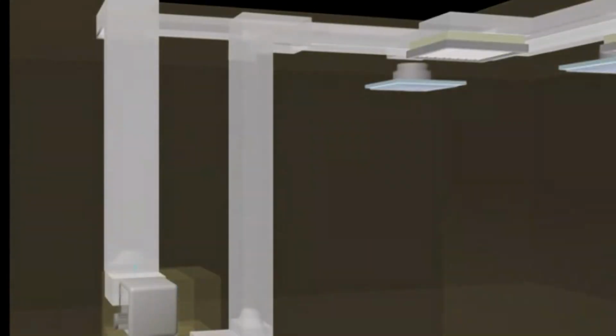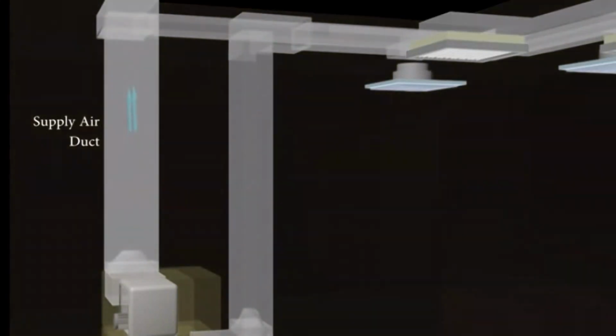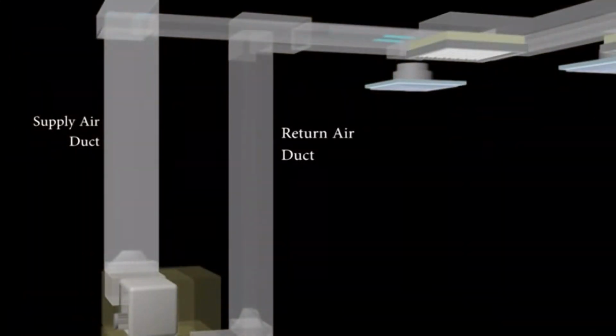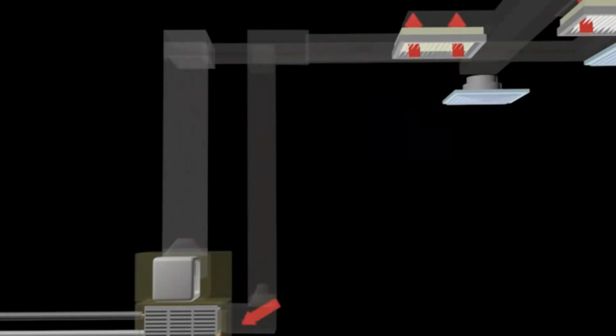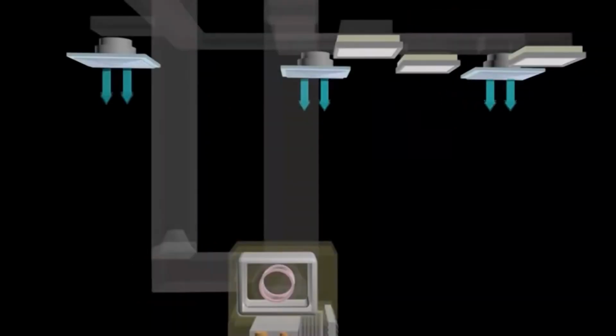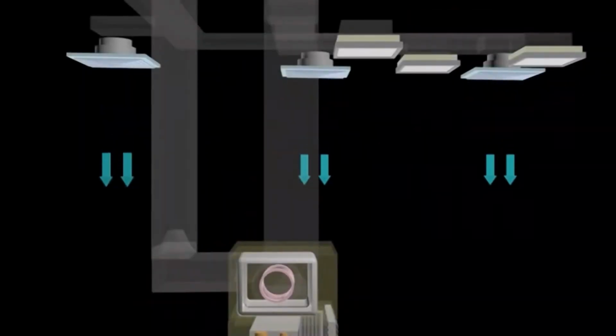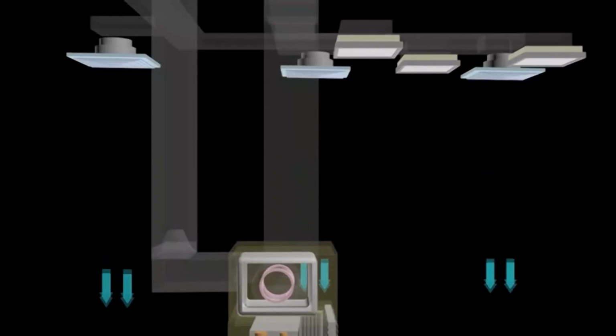There are two types of air duct which are supply air duct and return air duct. These air ducts are coated with insulating material consisting of fiberglass wrapping with aluminium foil. It reduces heat transfer from the environment to the air duct. Air returning to the air handling unit will pass through the filter before passing through the cooling coil and returning back to the room. This ensures that the air returning into the room is in a clean condition.